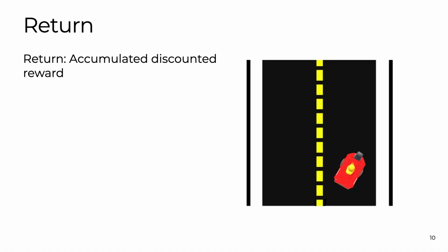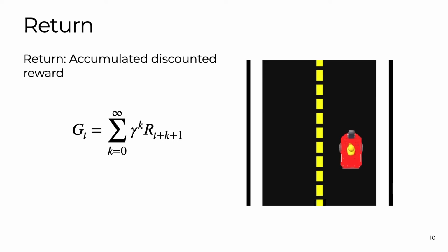We might not just care about the immediate reward though, since maximizing this might be very greedy and might not lead us to good plans in the end. As a result, we can define another variable G, which is the discounted sum of the rewards from now until the end of the time we care about, assuming we took some sequence of actions and visited some sequence of states. This is where the discount factor gamma comes in. Gamma has a value between 0 and 1 and controls how much preference we want to give to rewards that are obtained sooner. For example, if our duckybot is pointing at an angle, it might yield a higher return to turn first and then go straight, even if going straight right away might have yielded more immediate reward than turning.